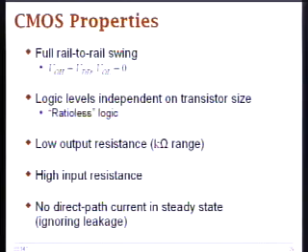Unlike, for example, ratioed logic, which has to provide a voltage level depending on the ratio of two transistors that are active, in which case they will have to dissipate some static current. But these are just some of the properties that we will get back to in the analysis of more complicated logic gates in full static CMOS implementation.